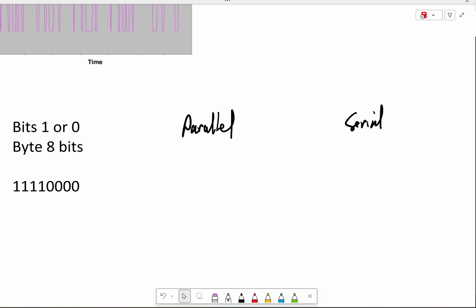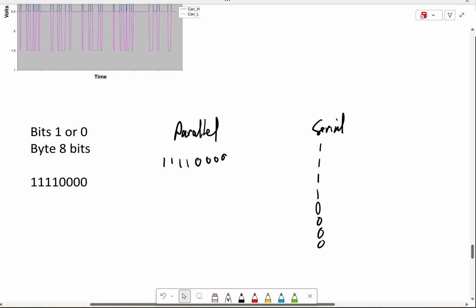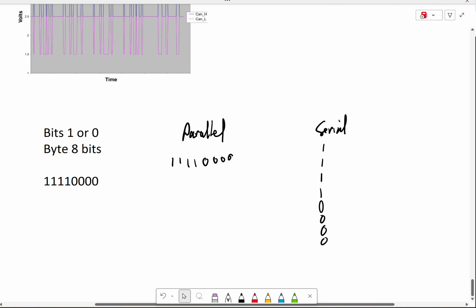Okay, so that would mean you'd have to have 8 wires. There we go. So each of those 8 wires is going to simultaneously carry that 1 byte of information from location A to location B. Okay, for serial communication, we have 1 wire, and everything goes in series, one after another, right? So you'd have 1, 2, 3, 4, 1, 2, 3, 4, right? That's what you'd have. When we're talking about different means of communicating, a lot of what we do nowadays happens via serial communications, like USB, for instance, a USB cable, universal serial bus.